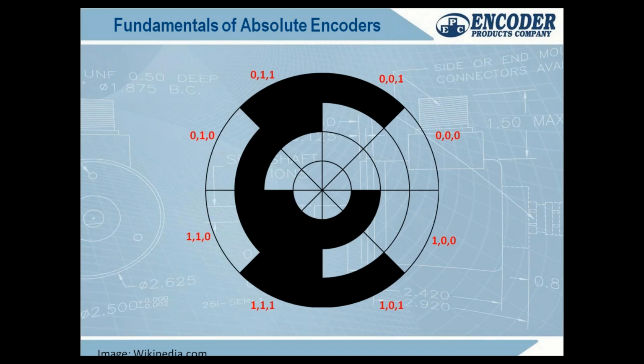This is an example of an absolute encoder wheel here. This has tracks. So unlike incremental encoders that just have, my pointer here, lines on the disk, absolute encoders have tracks, kind of like a record, right? This encoder has 3 tracks, 1, 2, 3, that are being used here. You would call this a 3-bit encoder. And what it does is if the light's going through, it will call each bit a 1 or a 0 based on if a photoreceiver detects light or not. So unlike an incremental where you had that one photoreceiver, there's actually a photoreceiver for each track. And if light is going through, it's a 1. If light is not going through, it's a 0.